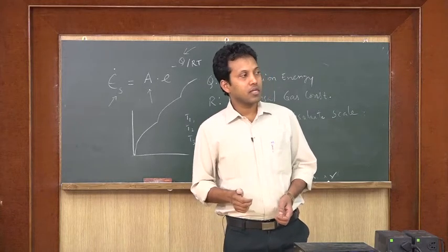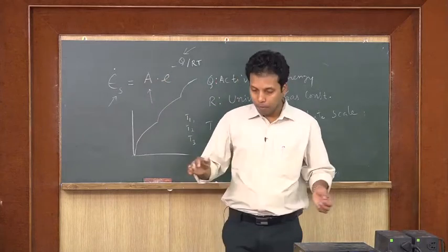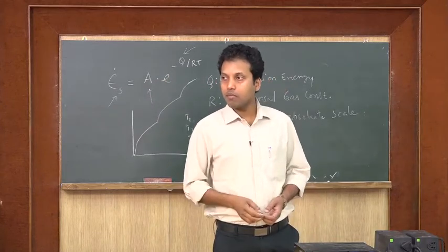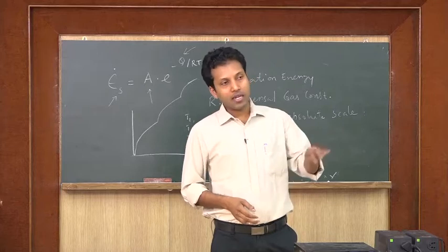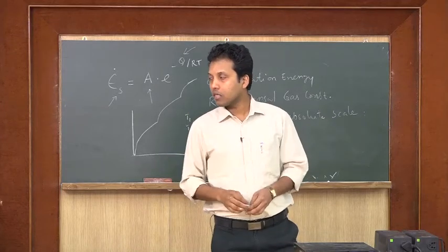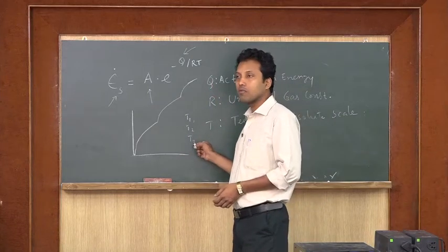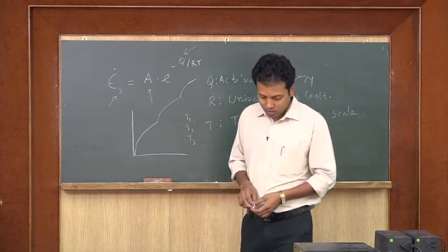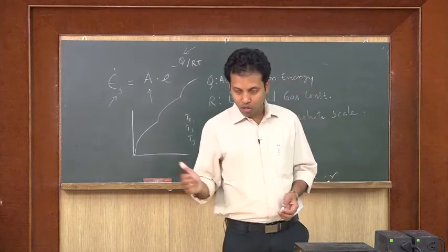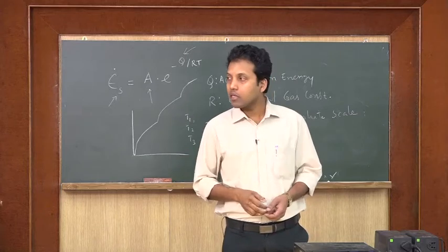Obviously, here low temperature means above the temperature needed for having creep in the material, and high temperature means a temperature close to the melting point of the material. So, we have seen that dislocation assisted creep or diffusion assisted creep takes place if we vary the temperature.